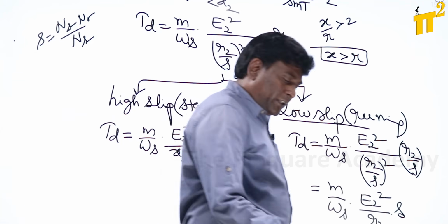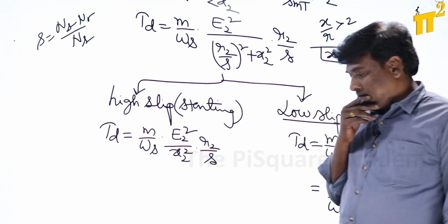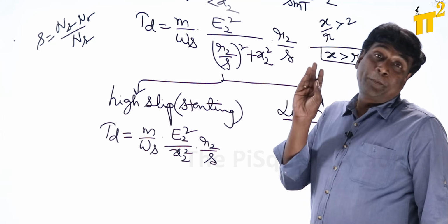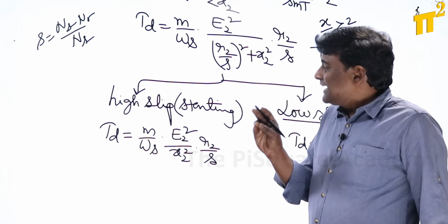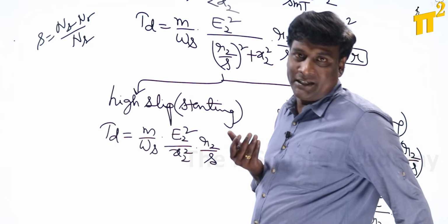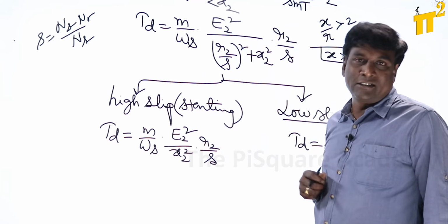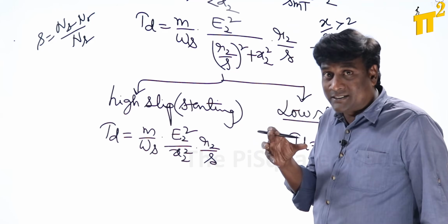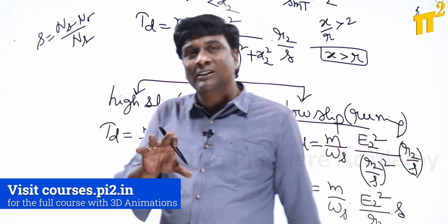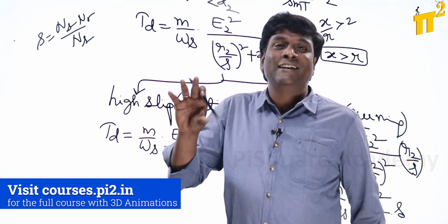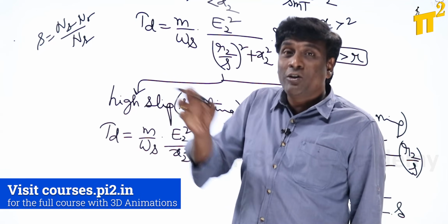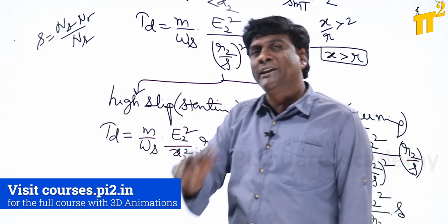Okay, now here one thing we have to decide: they can ask only starting torque, they can ask peak torque, okay, but they cannot ask during starting condition, because during starting conditions it's a transient period. For example, the moment you started an induction motor, at that instant, just about to start, how much is the torque developed, anybody can ask. But after that it will be accelerated. The rotor speed will accelerate towards synchronous speed. During that time of acceleration, in the transient period, nobody can ask any question.